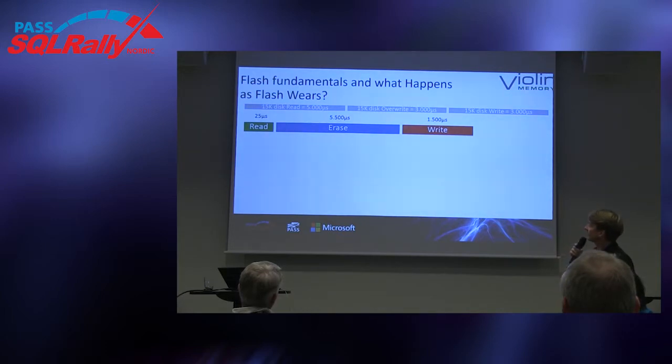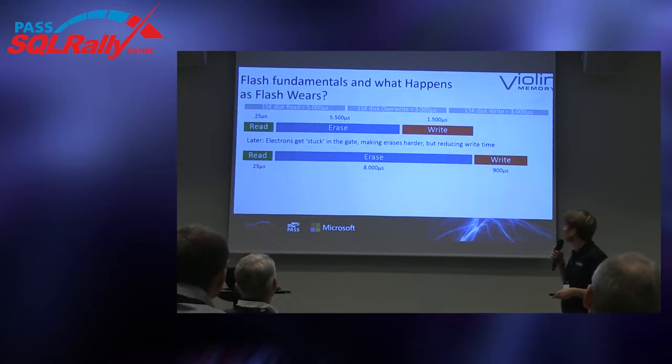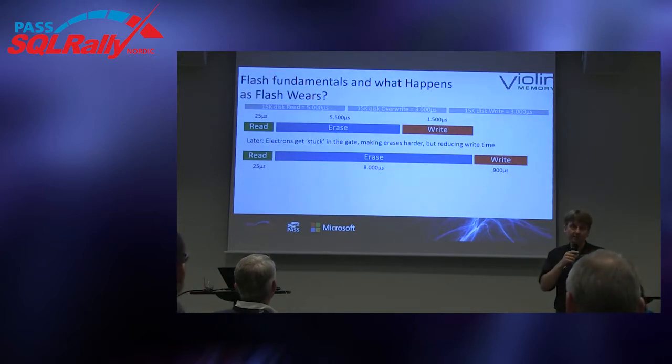This is in the beginning, and very quickly after a week or two, this is the situation. So the erase process plus the write process takes around 9 milliseconds. So if you've ever tested flash and did a lot of writes to it, you have seen this behavior. It is very slow at doing writes, or at least the latency will go up like a heartbeat. Sometimes it's very, very slow because this process is happening in the background. It's much slower than a 15K device.